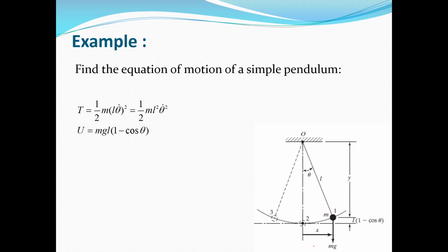So similar to the spring and mass system, we can extract the equation of motion, but this time we use the energy methods. The kinetic energy for this system, as you know, will be stored in the mass or in the rigid body with mass or mass moment of inertia.